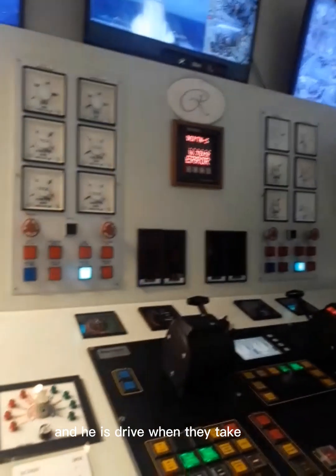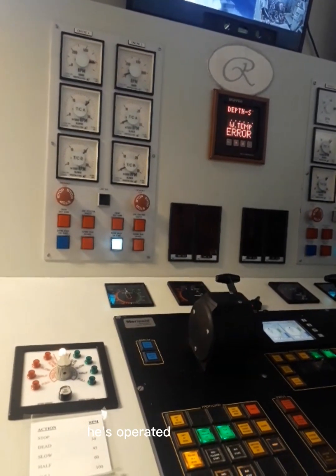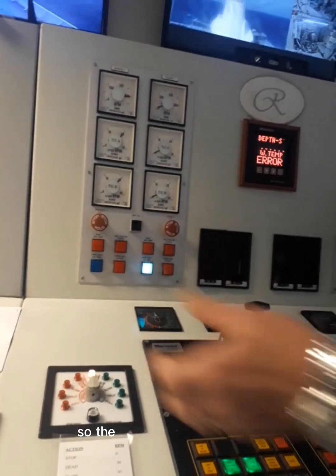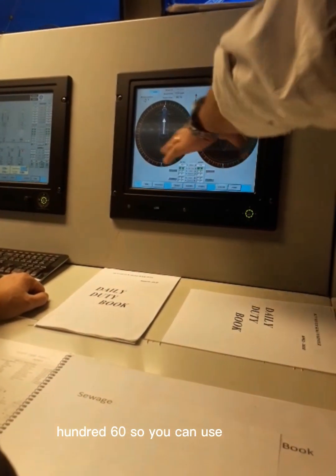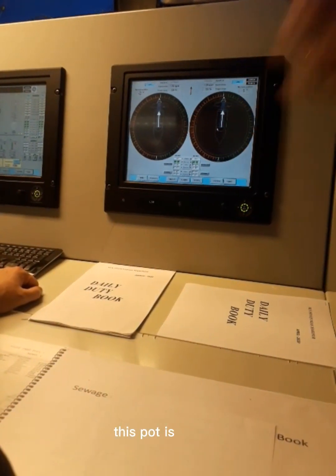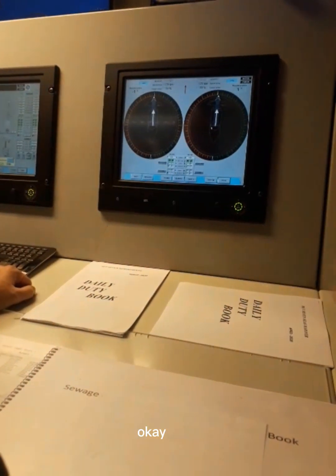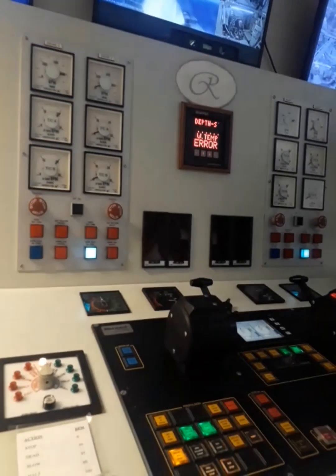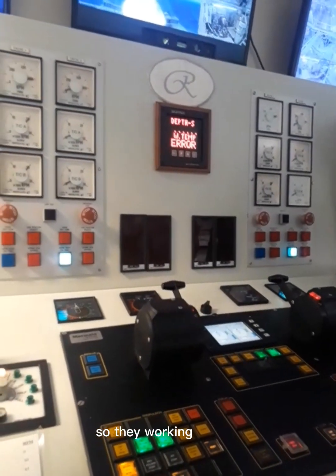But when they take manual, so the captain is operated during the maneuvering in port, he is operated by the two levers. Port pod, starboard pod. RPM, movement of the pod. So the pod you can put, you see how is the scale, 160. So you can use as steering. In this ship, the pod is the steering. Okay? They call the steering control diamond Cameva, but this one is the pod control. So they are working together.